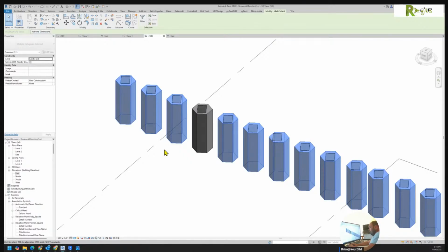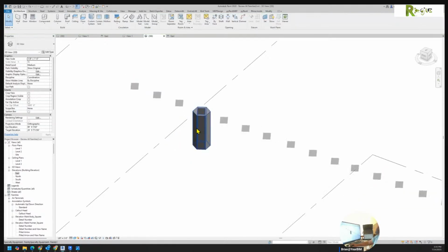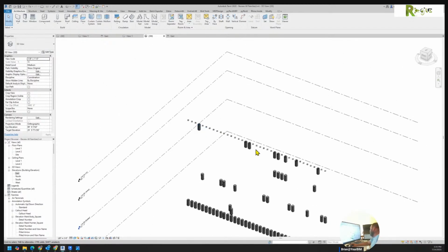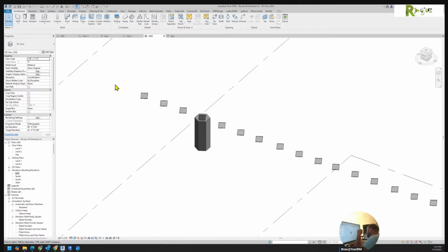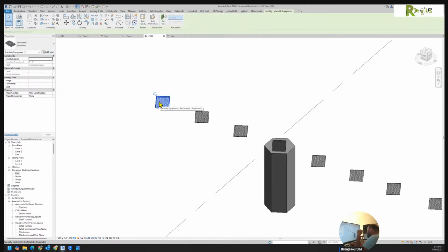So if we delete that, what we end up with, now that is a very unfortunate thing that I do not like about these face-based families. This I didn't understand going into the first 2 days of building those tables. And that's the unfortunate part. But face-based families, if you delete the object, this thing just becomes unassociated.